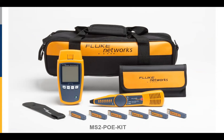I'll send a tone down the cable and I can find the port on the patch panel that it's attached to. This toning probe, I should have picked a picture that shows the bottom of it. The base of it has another RJ45 outlet, so I can plug in. It has 8 LEDs and it will beep through them to tell me if I've got continuity on all the conductors.